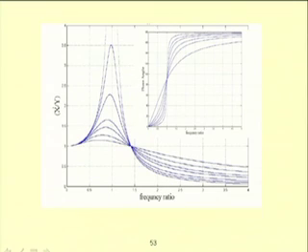In this case, if one plots x by y versus the frequency ratio, one can observe that with increase in frequency of the support, initially the response increases. If there is no damping in the system, then that amplitude becomes infinity, but due to the presence of damping, the response reduces. One can observe that irrespective of damping, the response x by y equals 1 at omega by omega n equal to root 2. After root 2, one can observe that with increase in damping the response amplitude increases.